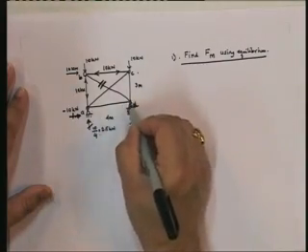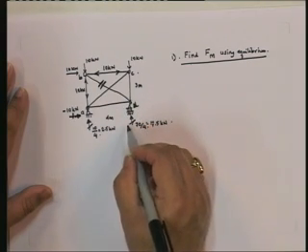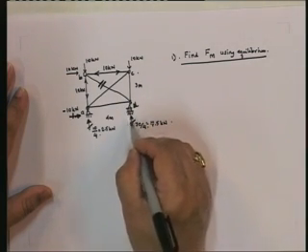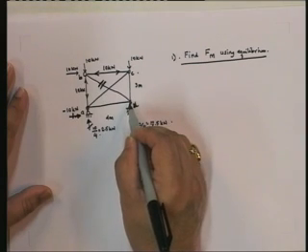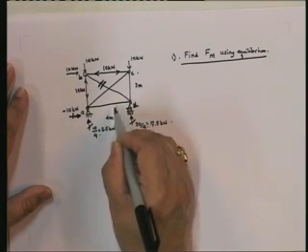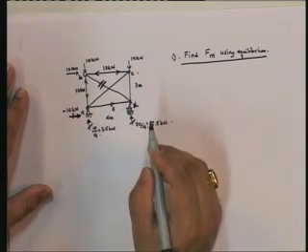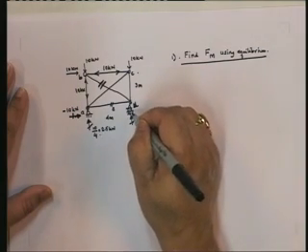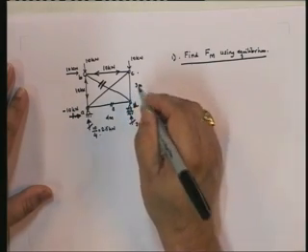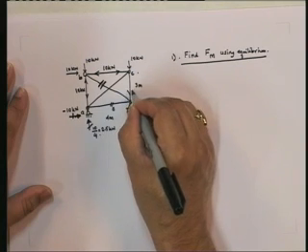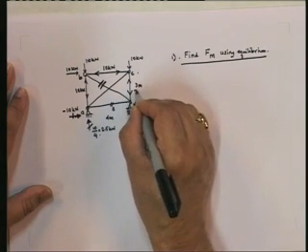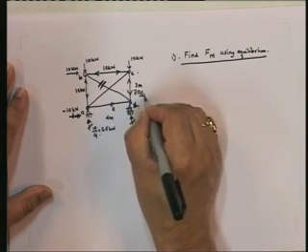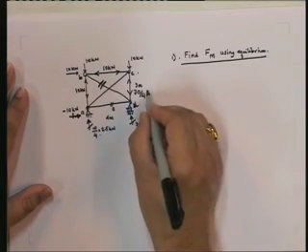Once you put it all together, let me forget about this, let's go here, let me go to this particular cross section. Here if you look at it, sigma Fx equal to 0 gives me what? This has no force. And if I find sigma Fy equal to 0, you will see that this is equal to 70 by 4 kilonewtons.